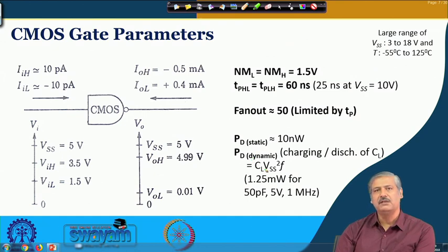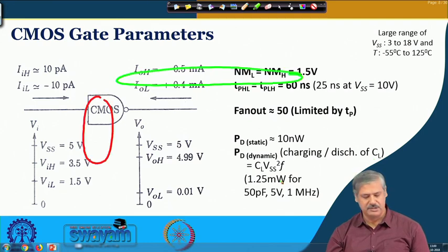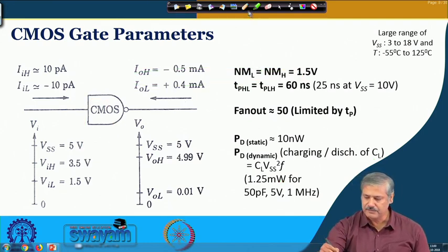So, together you get the dynamic power consumption because of the output capacitor getting charged or discharged, and the power that is getting consumed during the transition period, that brief time that you have seen when both of them are active, that being very abrupt, and so we can neglect that. So, roughly it is guided by this power that you see over here, and with high frequency it comes in the range of milliwatt and becomes comparable to TTL, okay. That is what we take note of here.